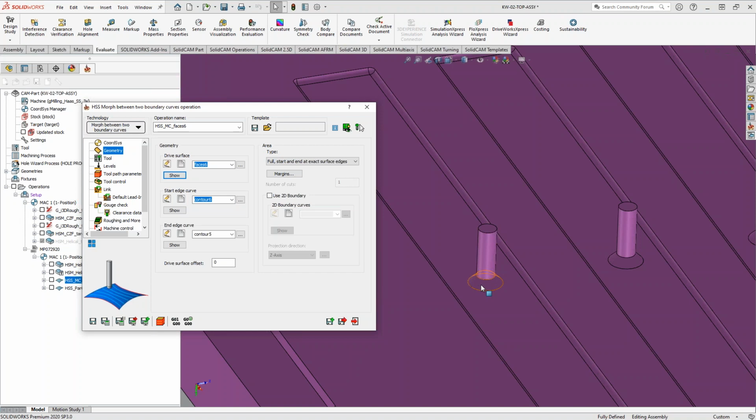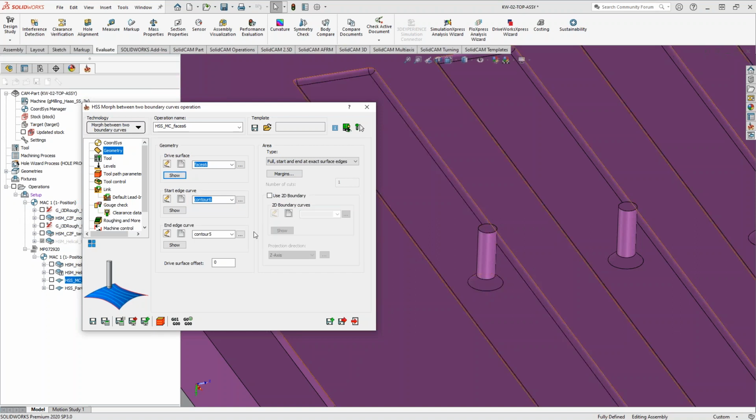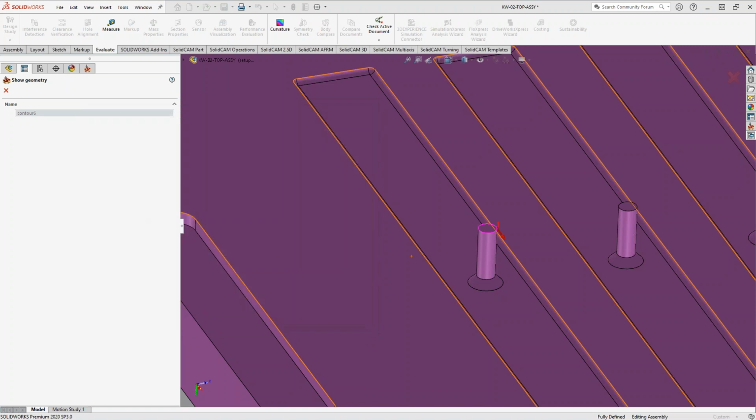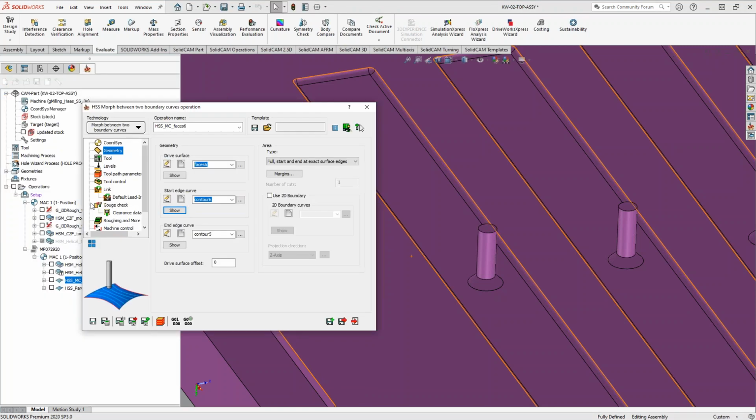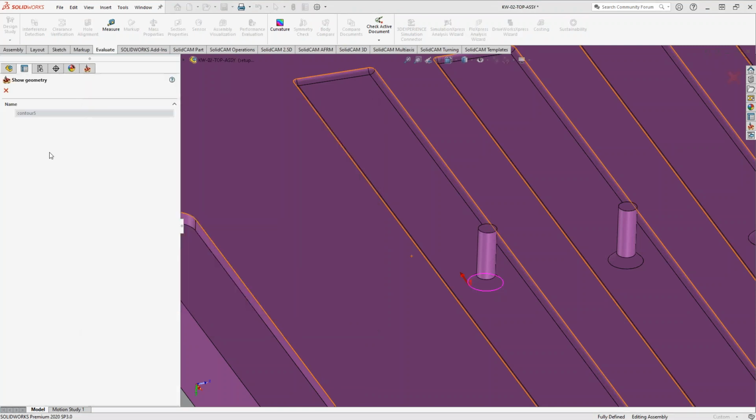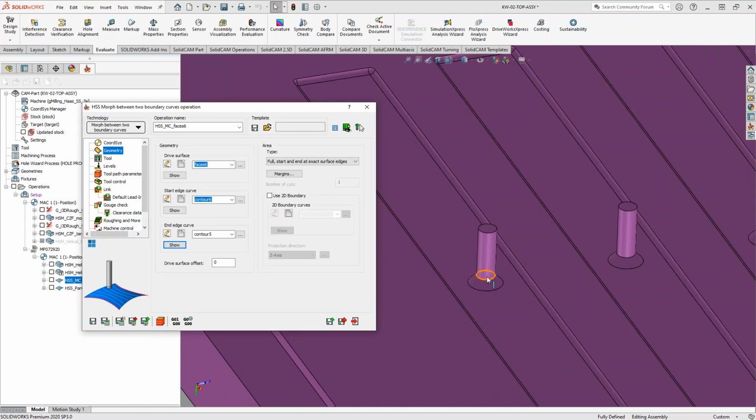But otherwise, it would have worked as well. So HSS is a good overall, whereas here HSM happened to actually work. But there's nothing about this that makes me think HSM. So that's why I wanted to show HSS on this. I chose the top curve there and the bottom curve there. So I'm basically just saying only apply the toolpath to that.